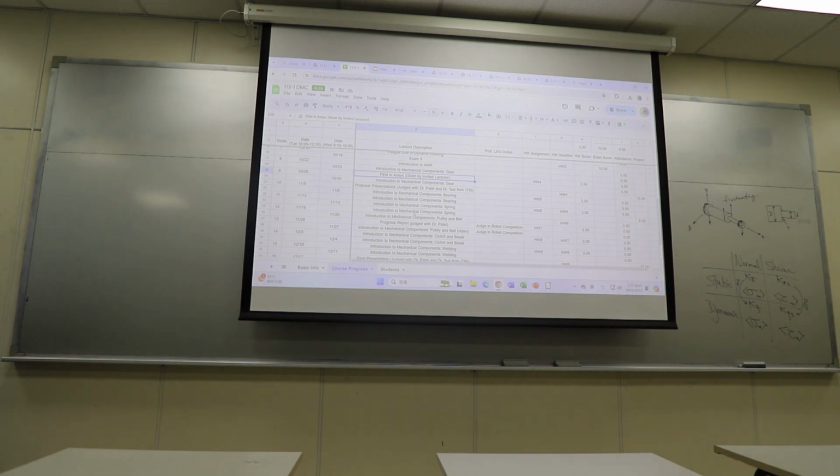As I remember, when researchers work on stress concentration in software and experiments, it's usually very difficult to use software to simulate the effect of stress concentration. So sometimes the analysis will give you stress results that are slightly lower than reality, because in reality there is some stress concentration.